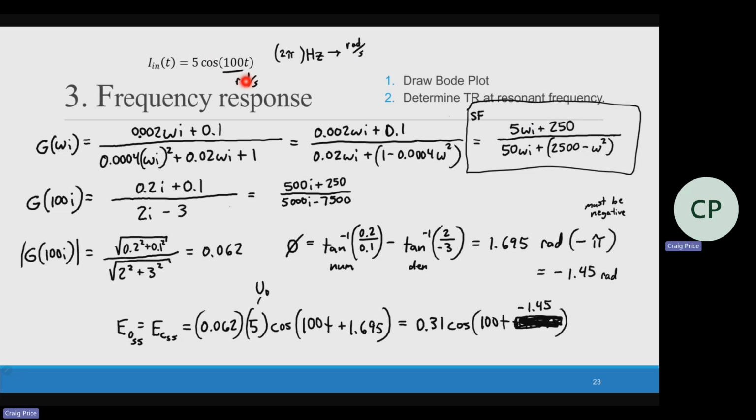Yeah, we still should get the same magnitude and same phase, even if it's in standard form or not. Now, standard form is going to be really helpful when we're doing the Bode plot. I need to have it in standard form to be able to find natural frequency, all that. So it's a good practice to do it right away. Not like me.